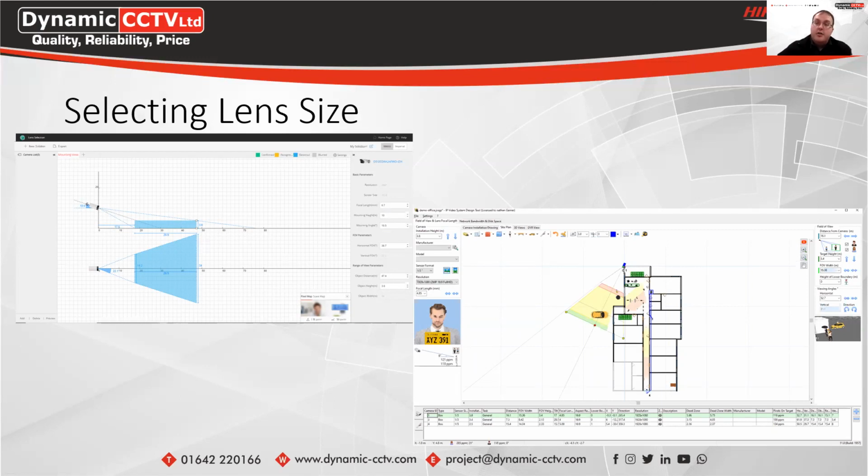It'll give you your angles as well at different distances away from the camera, because depending on the mounting height you will have a blind spot close to the camera and you may not get your actual optical image till much further away from where the camera's mounted. So the lens selection tool is great for being able to pick your lens sizes.